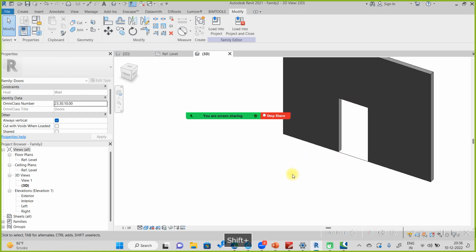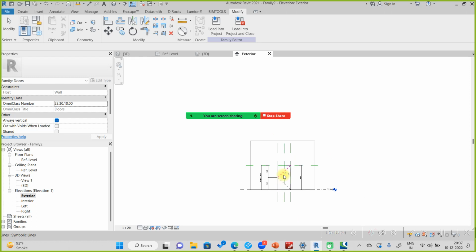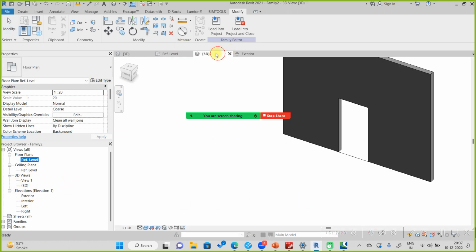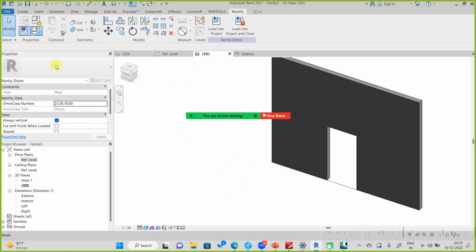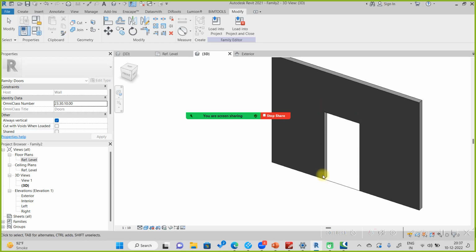Let's basically model a door, right? A door frame. First of all, let's see the elevation exterior. Here we see the height, and then there should be a width, right? So two parameters are already there. So if we check on the door family, change the parameter here, it will be 2500, 1200. You see, it will change. But now to the opening, we'll have to add the door frames and door panels and all of the stuff. Let's try on a new